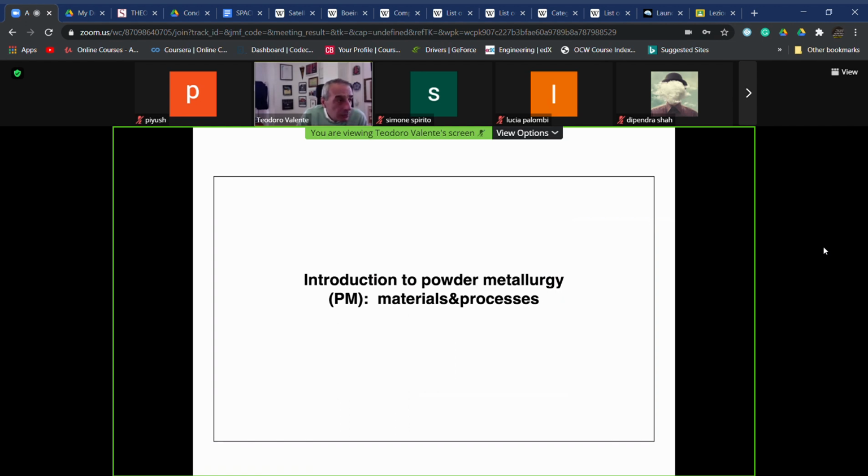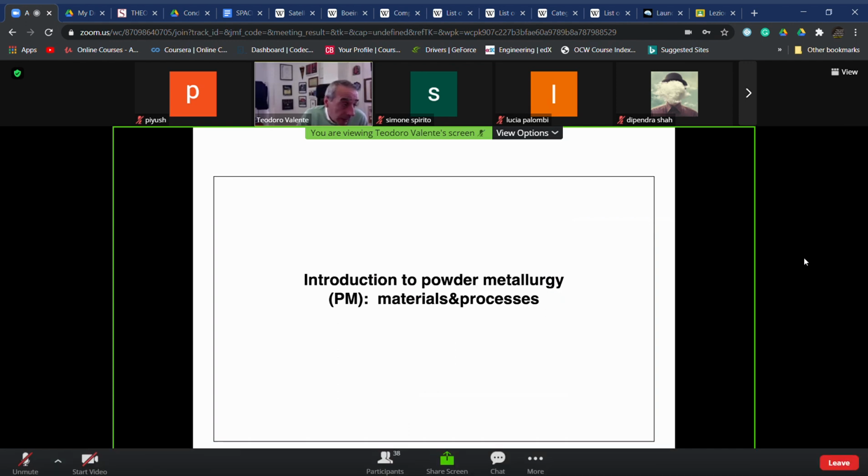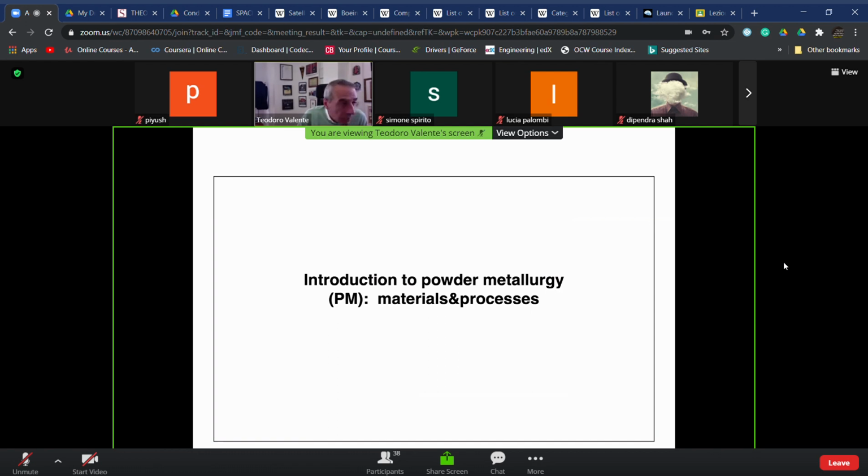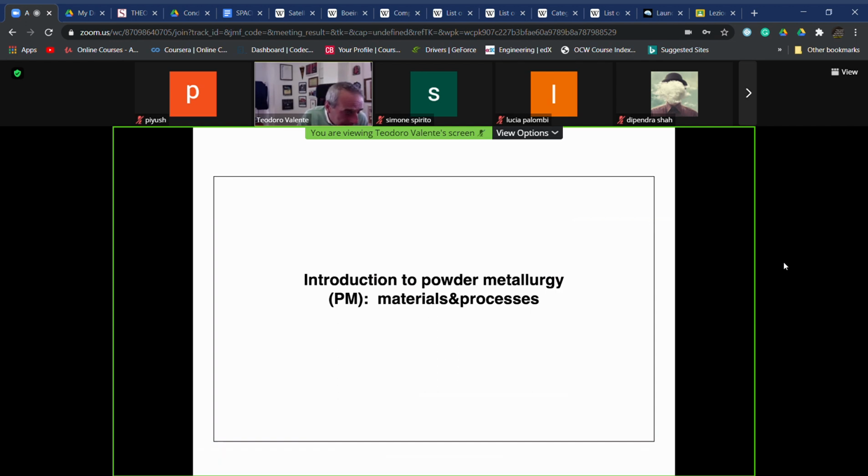And so we are not able to melt the ceramic phase, because if you think, for example, of zirconia, just to mention another ceramic material, and nickel-based superalloys, the zirconia melting temperature is around 2,700 Celsius. The nickel-based superalloys melting temperature is something around 1,500 Celsius. So in order to melt the zirconia phase, we should reach at least 2,800 Celsius. And you can understand that this is not possible.